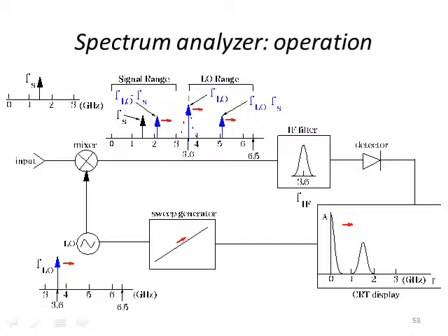We're going to have FLO, FS, FLO. We have our sidebands with minus and plus, and then we put it into our intermediate filter where we pull out the 3.6, go to our detector, analog to digital conversion, and you'll see that we'll pull out, so 0 would have been our 3.6 gigahertz oscillator signal, and then we pull out our signal Fs at the output of this system.